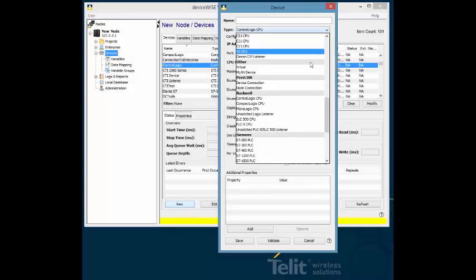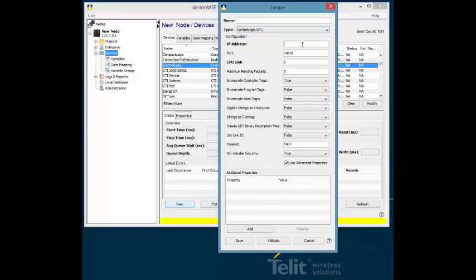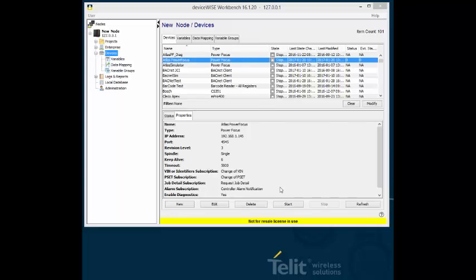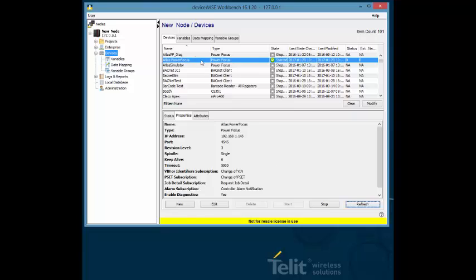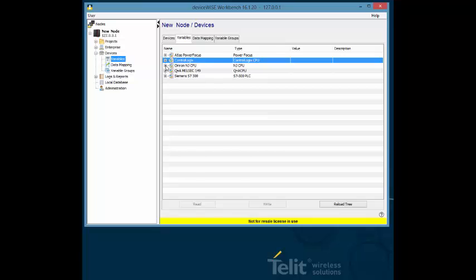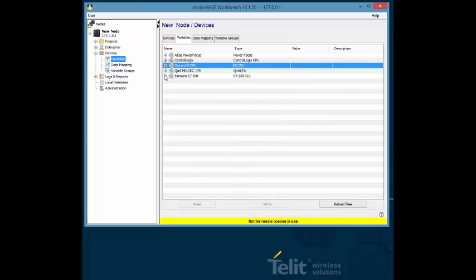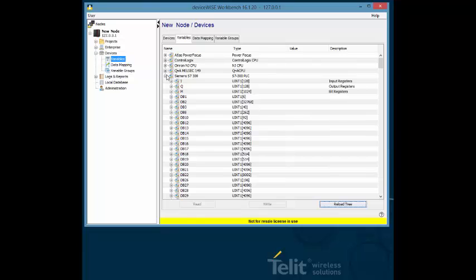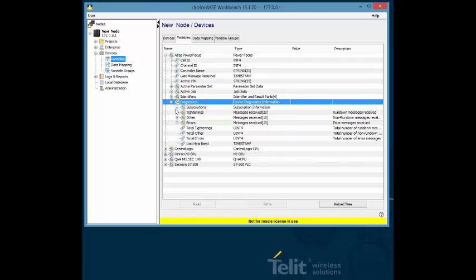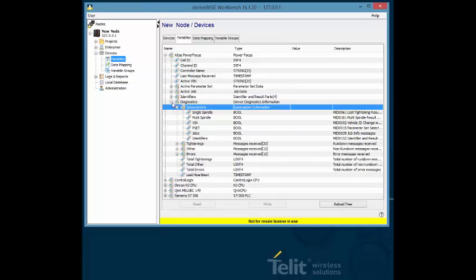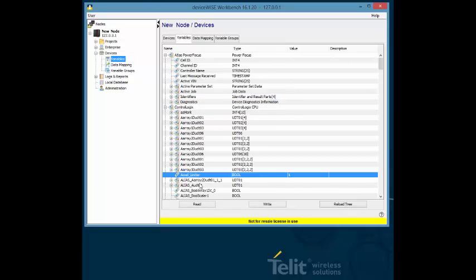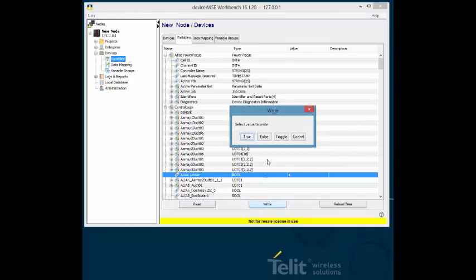Configuring a device in most cases is as simple as providing the device's IP address. Once a device has been defined, it can be started to establish communication between deviceWISE and the physical device. At this time, the device will be interrogated for its data tags, which will then be available for reading and writing. Subscriptions are made with the open protocol drivers to ensure deviceWISE is notified when tightening events occur on the DC tool controller. Using deviceWISE to configure a device connection is the first step in tracking the usage of your manufacturing assets to ensure you don't miss scheduled maintenance activities.